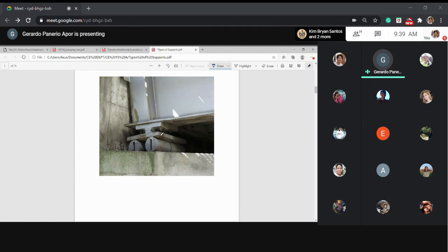And you know, the frictional resistance is dependent on the coefficient of friction between the material and the normal force of the beam. So the normal force here is the reaction. If the reaction is big, sometimes it is difficult for this point to move horizontally. So as a solution, the designer puts a roller, okay, so that it is free to move.